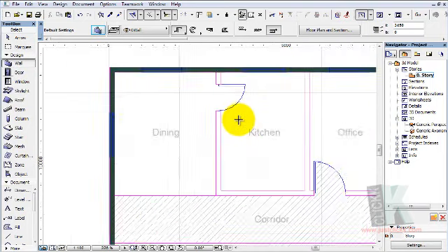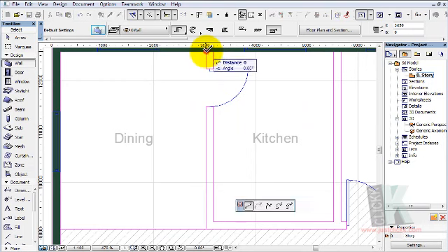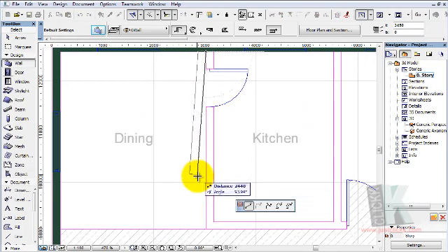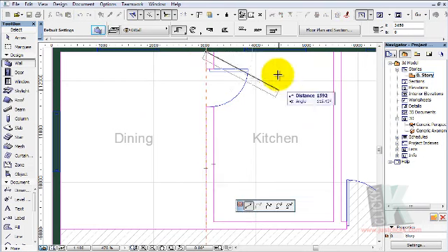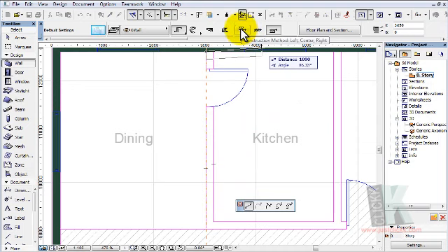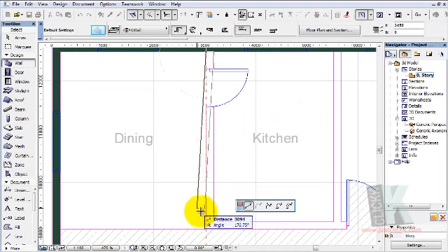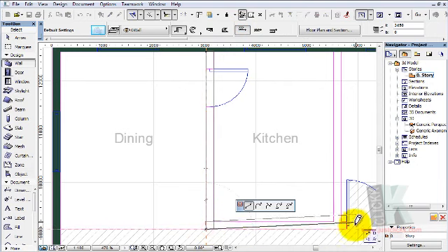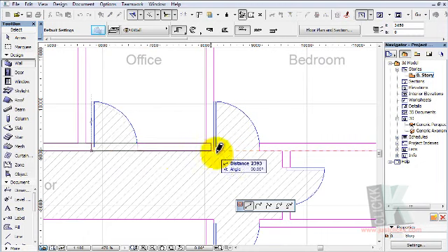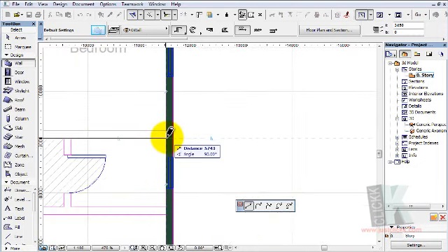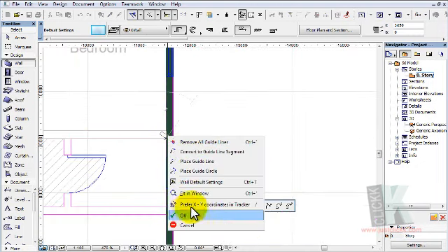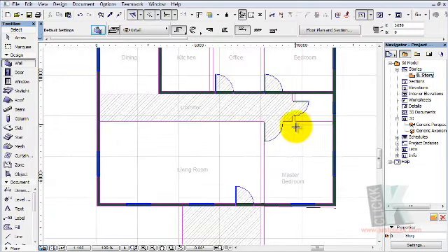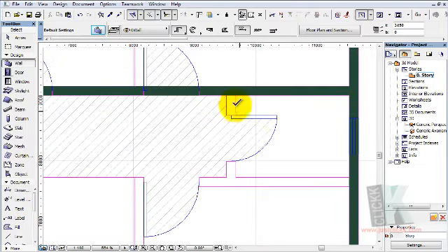So I can also go ahead and begin to run the internal wall. Yeah, I've clicked at a wrong choice. Let me choose this alignment, which has repositioned it properly. So I can run this wall like this. This wall is supposed to continue to this end. You can right click if you want to terminate this continuous wall. You can right click and choose OK, and then it will terminate. You can continue with this here.